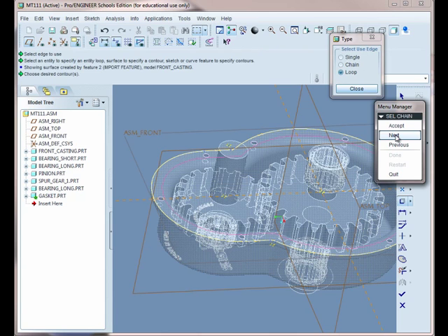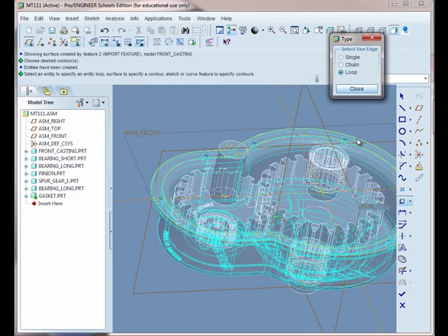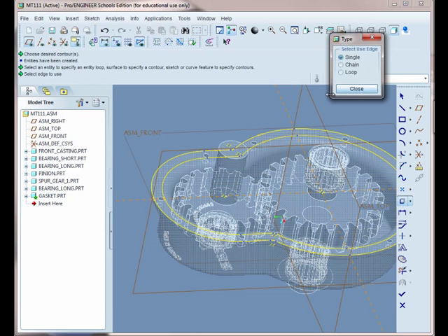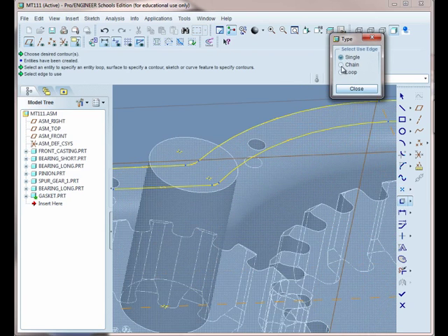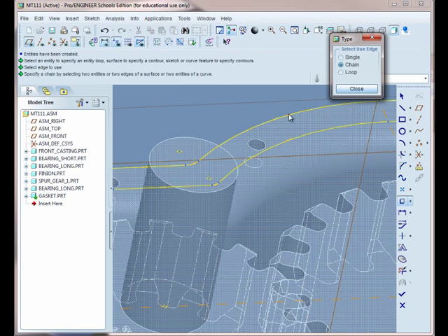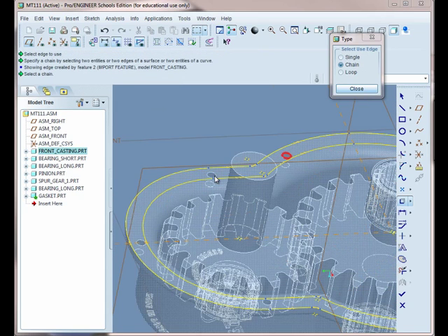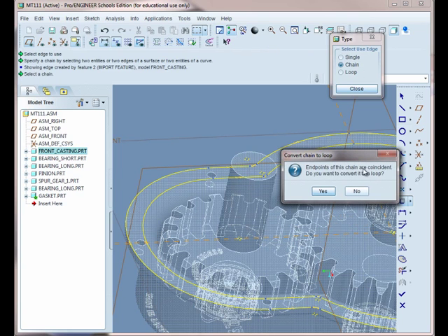And you'll see what that looks like in a moment. And there it goes. So I hit next, and we can see there's a pale purplish line on the inside there. Hit Accept. And now we just need to get those holes. So go to Use again, and we'll do the single. Actually, these are broken up into several surfaces, so maybe chain might be a better option. So I'll click there, and there, that grabs the hole. I'll accept that. And it'll give us a little message.